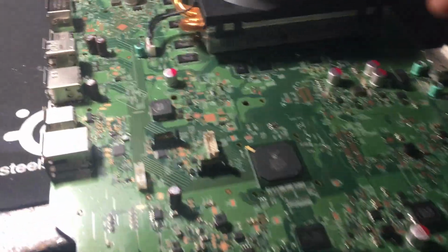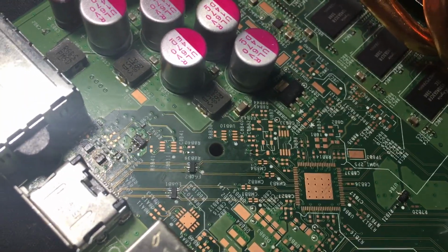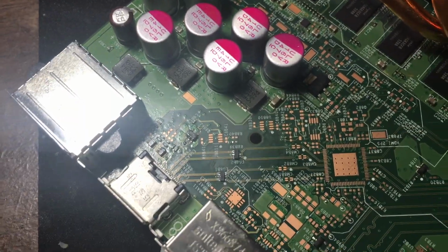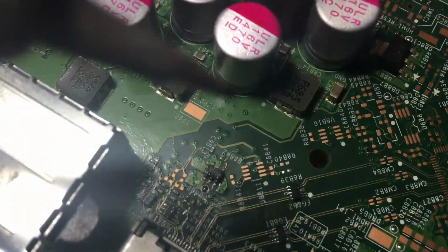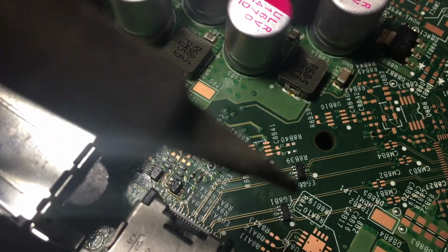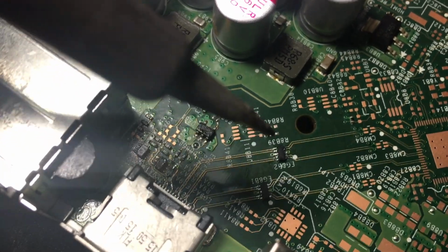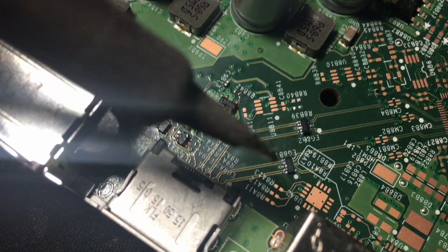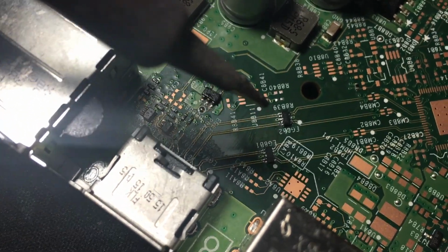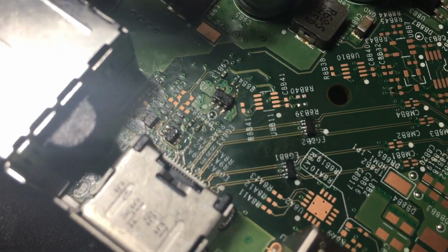but anyway, so the next thing to do, this is completely stripped down with the exception of the heat sink and the fan, just to be able to get access to that. I will say these are not easy to solder in. They're very tiny, and the soldering iron, at least the one I have, is ginormous. It's really big, so it's hard to get in. You basically have to put a good amount of solder on the end of the soldering iron and run it across all the pins, and do that several times, and it'll get enough solder in there. There's a tiny little bit of pad showing on the left and right side of these chips, and you can get some to attach. So I would do that, and then with the flux, I have some flux here. I use flux to keep everything nice.